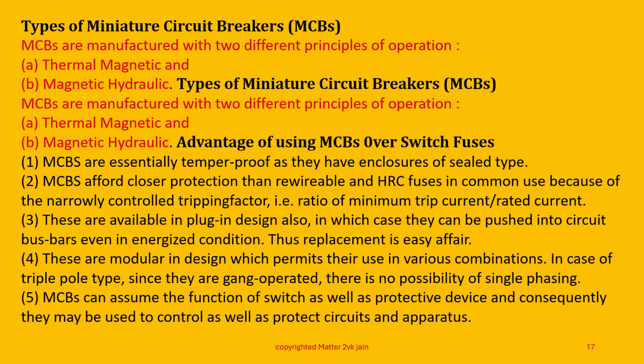In case of triple pole type, since they are gang operated, there is no possibility of single phasing. Next, MCB can assume the function of a switch as well as a protecting device and consequently may be used to control as well as protect circuit and apparatus.